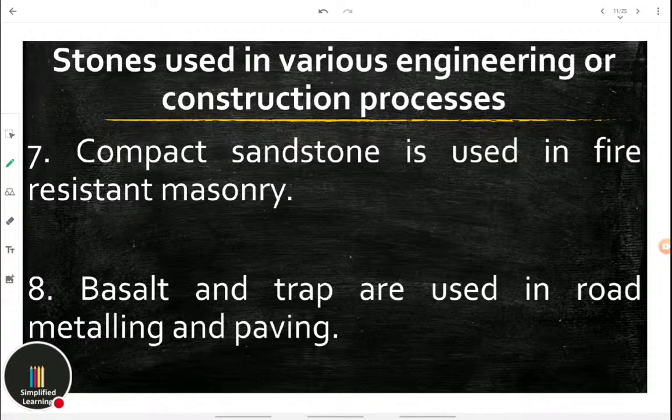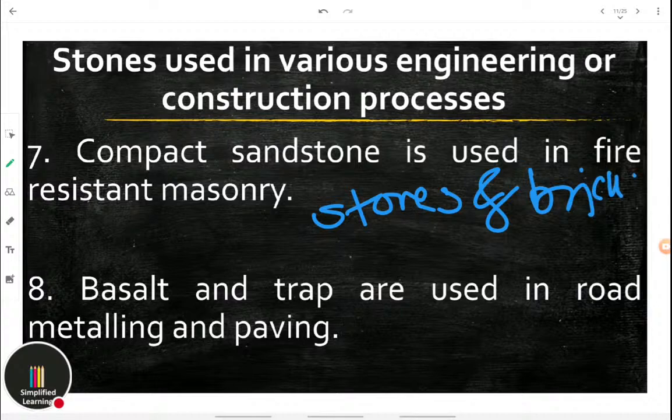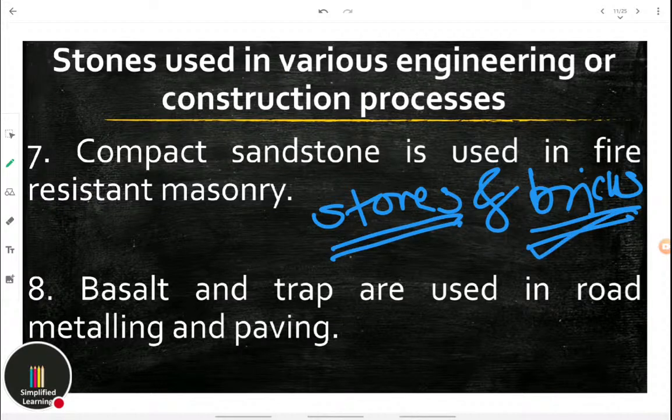Then compact sandstone is used in fire resistant masonry. See, when we are talking about fire resistance, actually stones are not that good. If we compare stones and bricks, bricks are better fire resistant than stone. But in case we have to use stone, then we will go with compact sandstone because of its fire resistance.